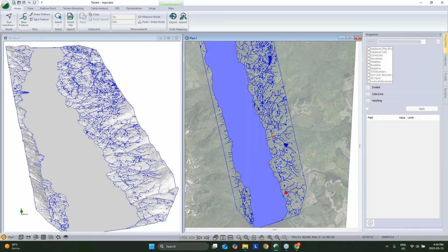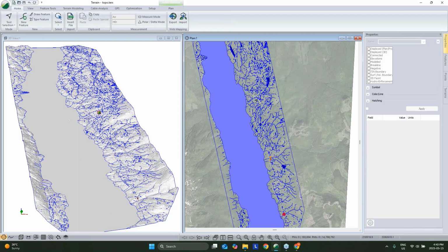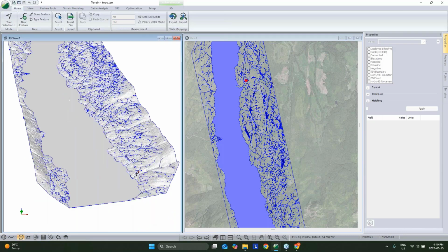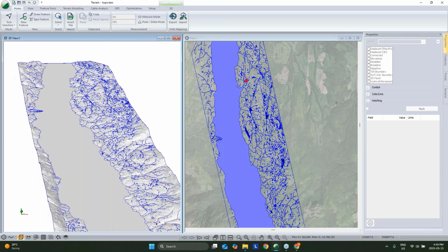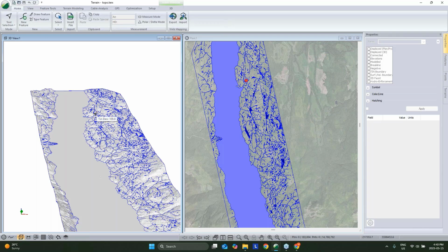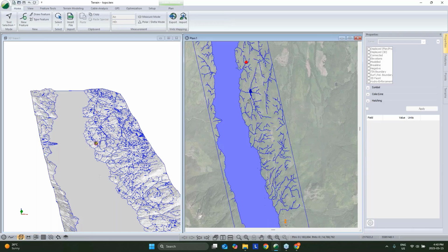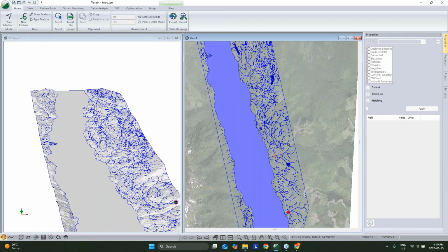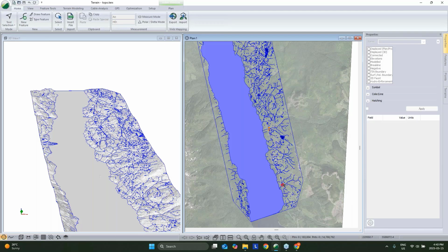And if I were to define my start point and my end point and let this thing go without any construction zones defined, I would expect the software would find the cheapest solution is to go from here down onto this flat spot and pop back upwards. Convenient. Now, of course, that is a lake. It's going to be really expensive to build a road in a lake, and practically speaking, it's probably better if we just avoid it and put in a firm do not go there.